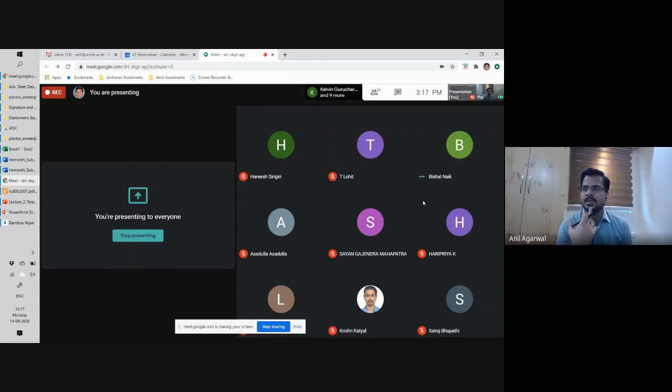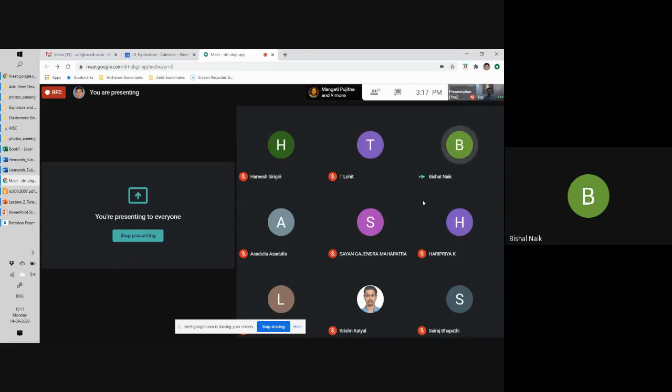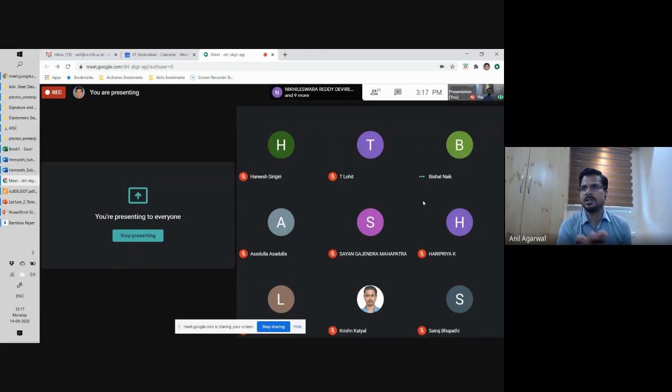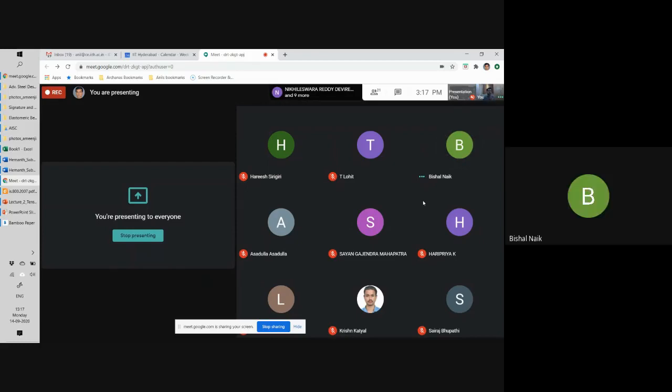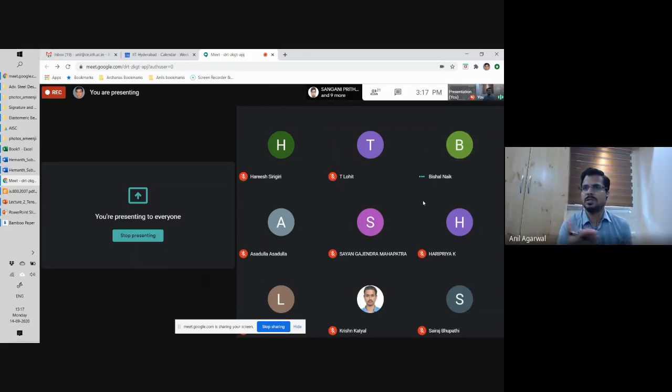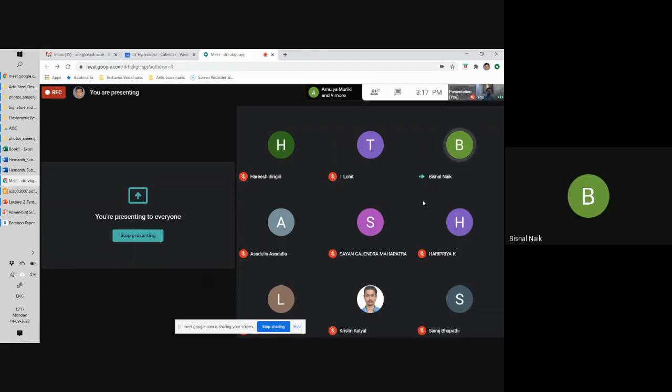What happens at yielding? Does it not yield, like it will not yield at all? Before it goes to rupture, it will have to go via yielding, right? Because the stress strain plot for steel is such that before you go to rupture point, you have to go through yielding. You cannot jump from zero stress all the way to yielding or all the way to rupture. So you have to go past yielding, right? Yes, sir.